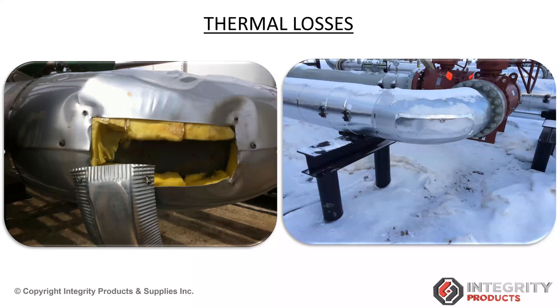And another thing about the losses from the system, as I mentioned earlier: the inspection port that is improperly installed, and especially the port that is missing the insulation from the system, the cutout insulation, can be subjected to thermal losses.